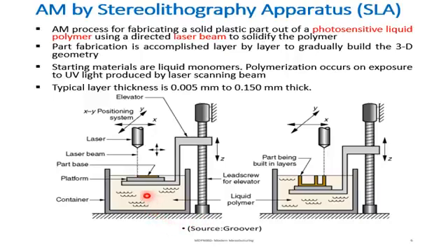So in this position here, a very thin layer of the liquid polymer is exposed to a laser beam, ultraviolet light produced by the laser, and this will cause the photosensitive liquid polymer to become solid. Of course, the beam itself from the source can move in the X and Y directions to scan a surface, the layer under consideration.